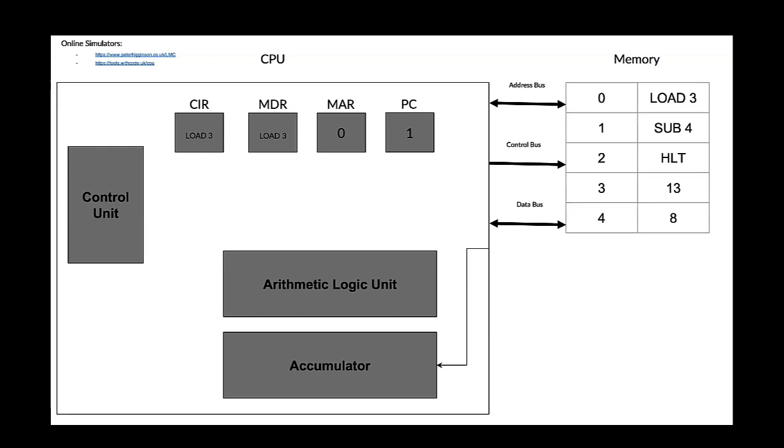The accumulator is a special purpose register, which is like a warehouse where data is temporarily stored while mathematical and logical operations are performed by the ALU. The ALU uses the data stored in the accumulator to process calculations. Now the control unit has the instruction, which means the decode stage is complete and it can tell the other components to execute the program instruction.